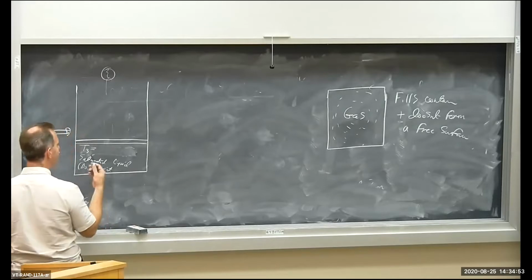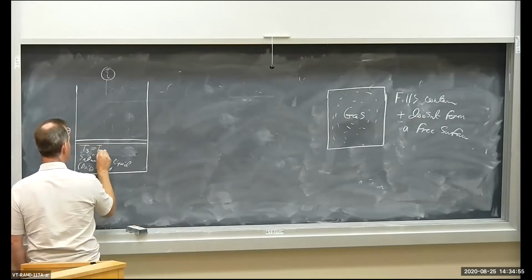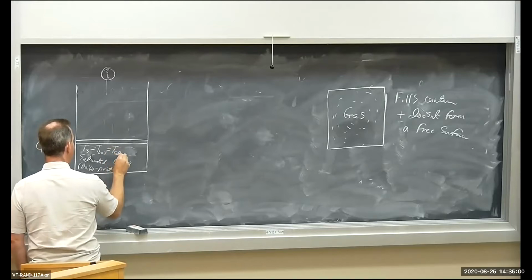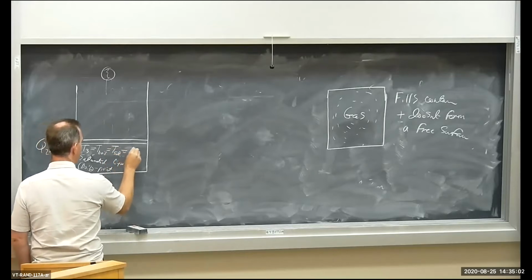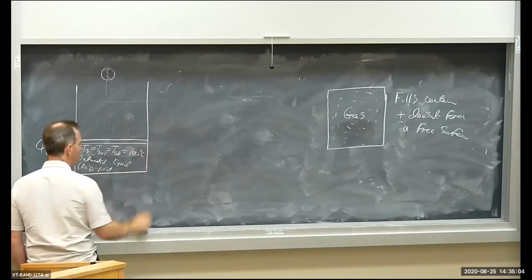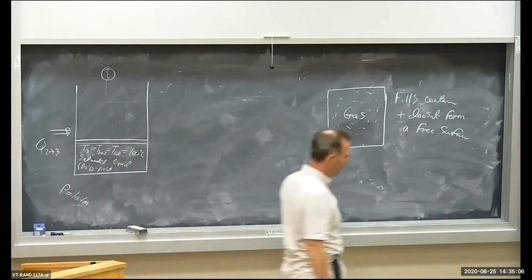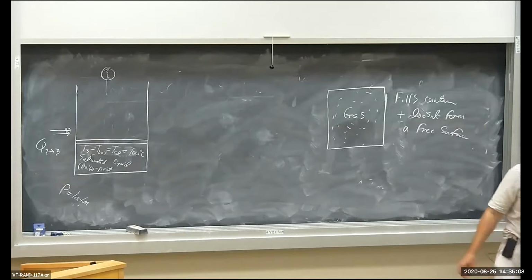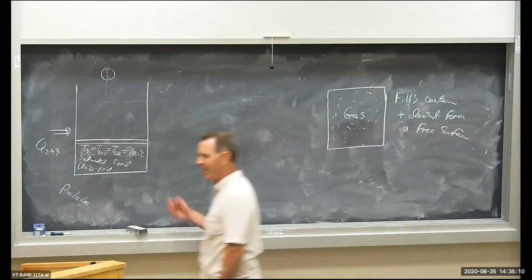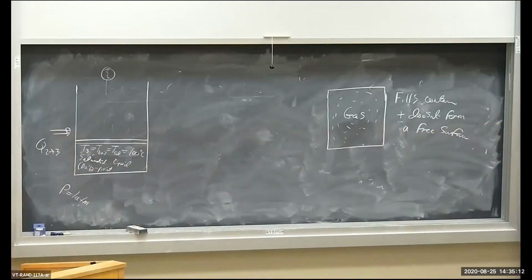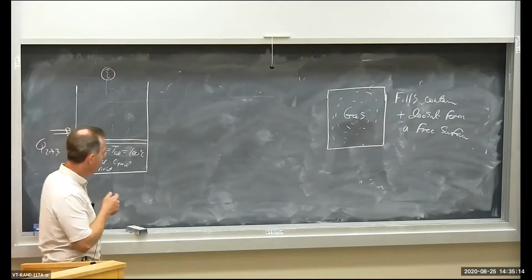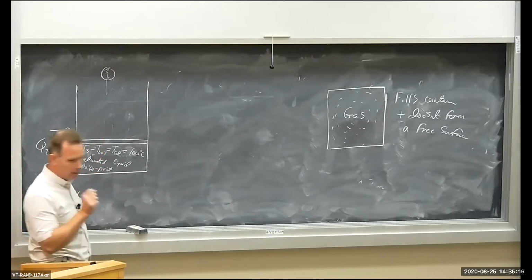It's the boiling temperature. T3 equals T boil equals T saturation, 100 degrees C. So we're going to heat it up to 100 degrees C by adding just a little bit more heat. It's liquid, but it's saturated liquid, just ready to boil.